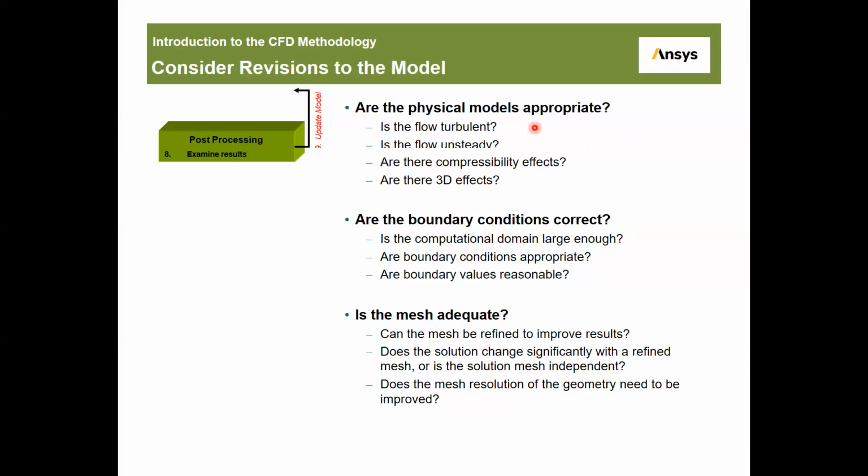Okay, you increase the mesh until your result is not changing with the mesh numbers. Right? That means the mesh is adequate. Right?